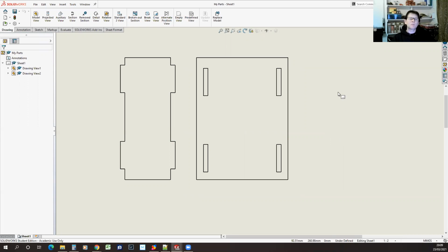And so the edges of the sheet tend to be thicker than the middle because it kind of bows down in the middle. So what you actually find is, depending on where in the master sheet that was cast your piece of acrylic has been cut from. So if you buy, say, an A3 sheet of acrylic from a supplier, it's probably been laser cut out of a much bigger cast sheet that was made in the factory. If it was from near the edge of that sheet, it might be up to 3.3mm thick. And if it was from the middle, it might be as thin as 2.8.